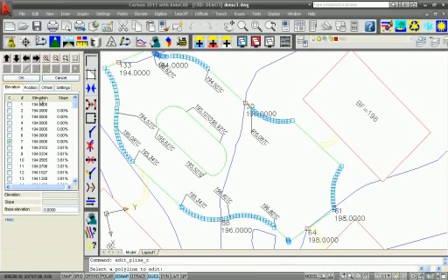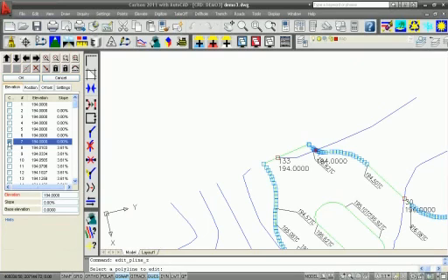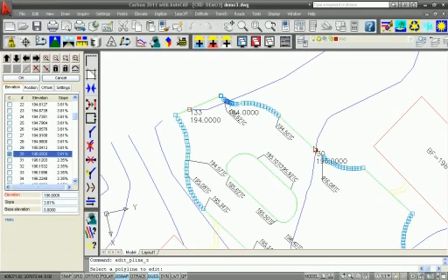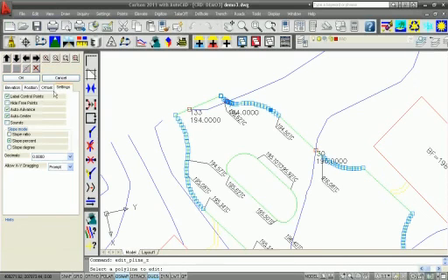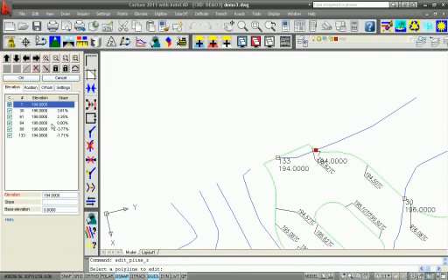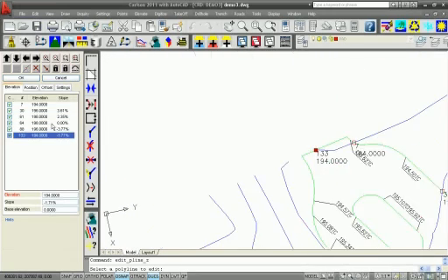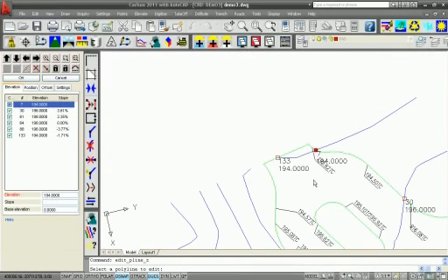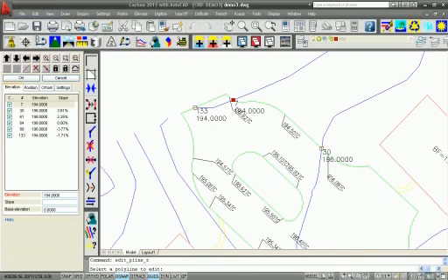I click on this line. I can see all the points on here. So anything that's checked is one that's been set by those contour lines. So 194, and I can go down. Here's 130. It shows me on the screen highlighted where that point is. And then all these points in between are interpolated. And one setting we have here is hide free points. If I look at those elevations, now we just have a list of the control points, and I can cycle through. But we don't want to use just those points.